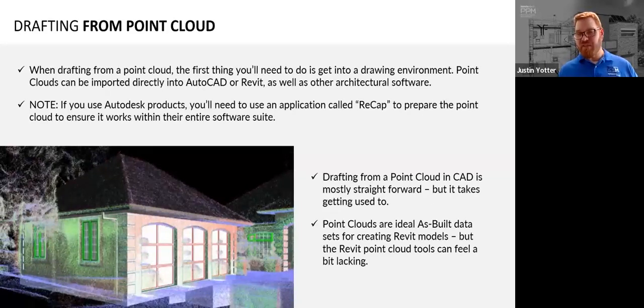Point clouds are ideal as-built data sets for creating Revit models, but the Revit point cloud tools can feel a bit lacking. If you're making a 3D model, it only makes sense to work from a 3D point cloud to create an accurate model to kick off your designs and planning. The tools for visualizing the point clouds are not as robust as they are in AutoCAD, which is a little weird, but nevertheless, point clouds and Revit do go hand in hand.